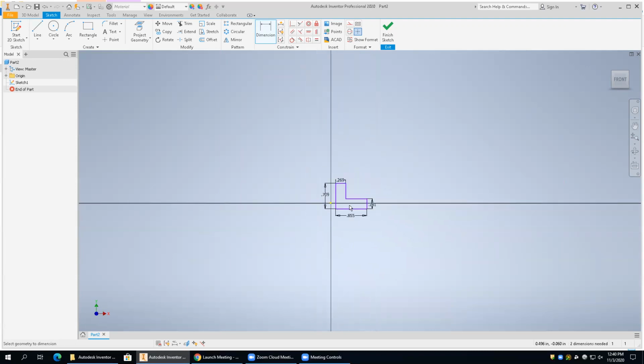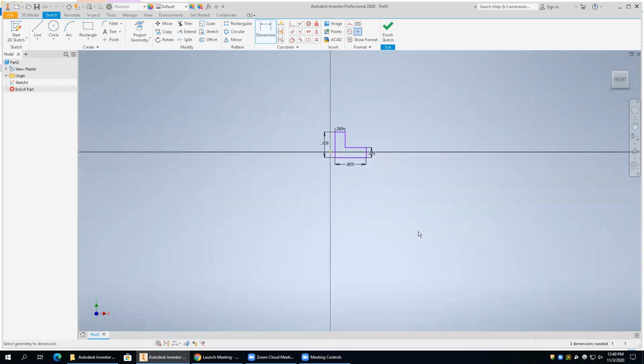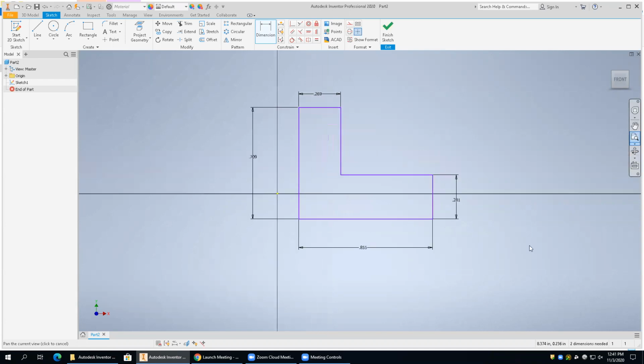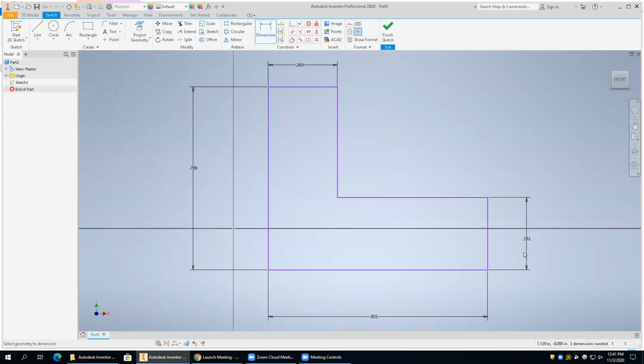Over on the other side here, we have zoom tools. If you open up that guy, this zoom right here is basically what's called a real-time zoom in AutoCAD. So it'll just allow you to, actually that one didn't do anything. Zoom all, let's take a look at zoom all. Zoom all is basically a zoom extents in AutoCAD, okay? So it's gonna show you the full view.